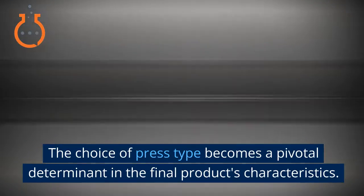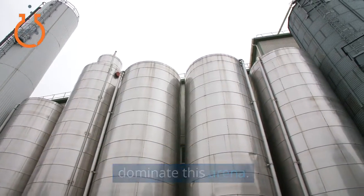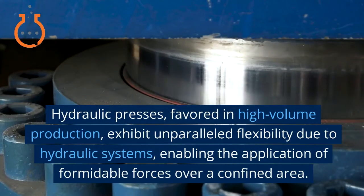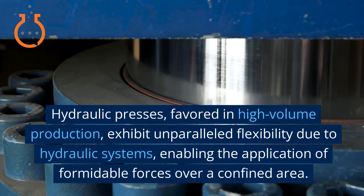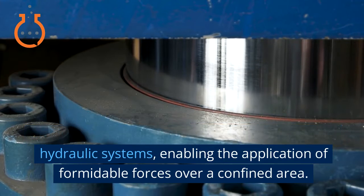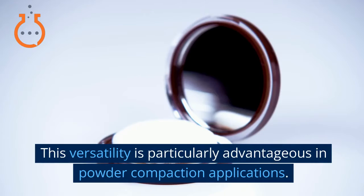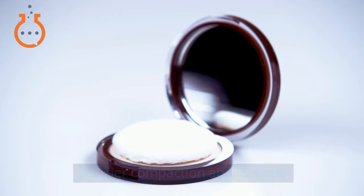Compaction equipment. The choice of press type becomes a pivotal determinant in the final product's characteristics. Two primary presses, hydraulic and mechanical, dominate this arena. Hydraulic presses, favored in high-volume production, exhibit unparalleled flexibility due to hydraulic systems, enabling the application of formidable forces over a confined area. This versatility is particularly advantageous in powder compaction applications.